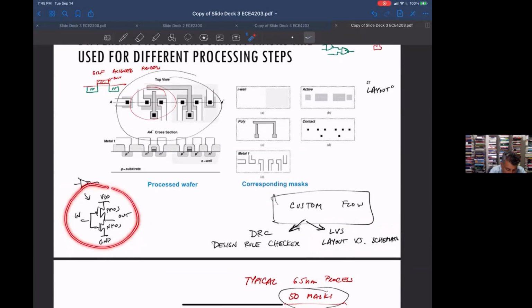You draw the schematic, you run SPICE on it, and so on. You typically don't use something as simple as PSpice, you use other pieces of software, but it looks like what you would draw there. And it compares it to your layout. Even in a custom flow, you're typically dealing with hundreds, if not thousands of transistors.